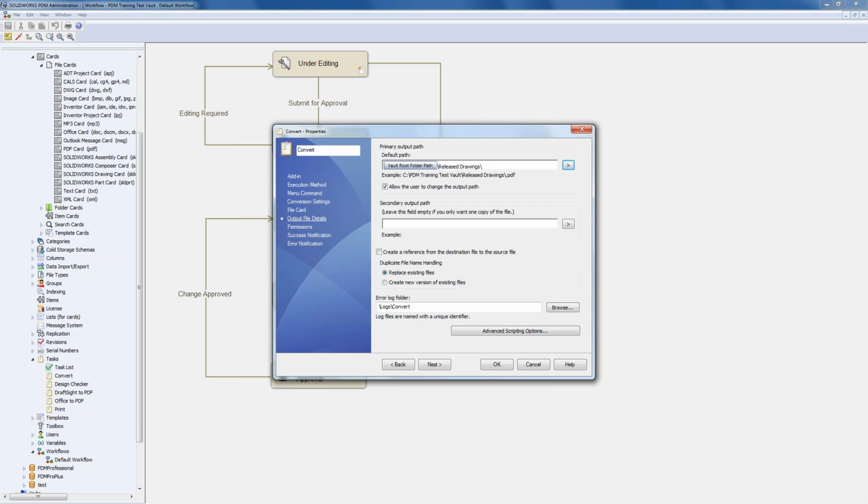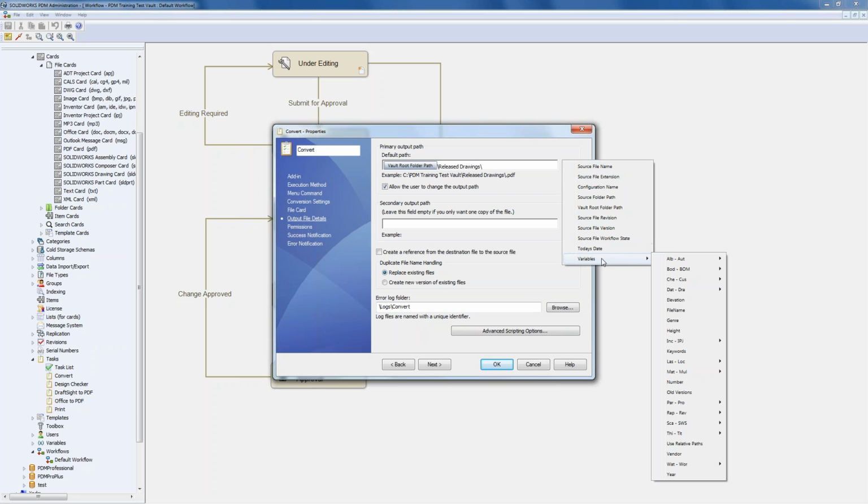drawings, and do /. And at that point, an interesting thing is if I did want them broken out by project, because all of them are getting their project number driven into there, I could actually add variables at this time and add project number as an example folder, if that's reliably on all those files. That's a new thing in the 2017 task automation, by the way. So again, if you've upgraded to 2017, you're not seeing this. It's because you haven't upgraded the specific convert task side.